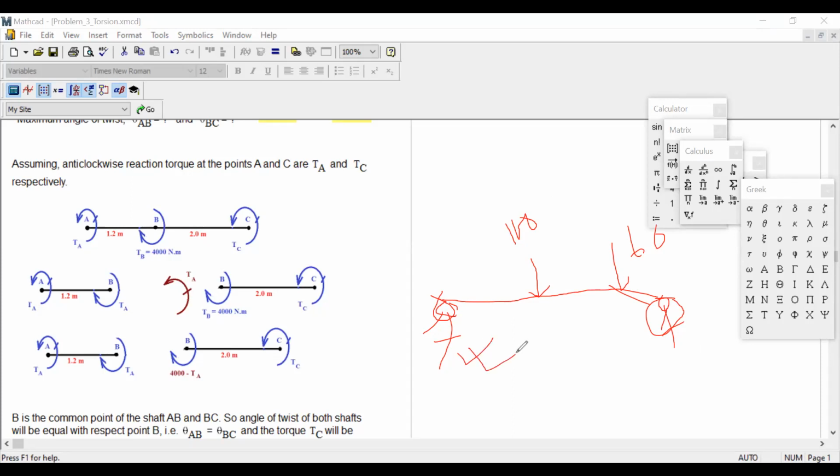But in torque, even if you take moment, this is not force into distance. We apply torque. So even if you take moment over here, TA should not be 0. Right? That means you have three values, TA, TB, and TC is unknown. So by taking moment or summation of force, you cannot figure out the value of TC and value of TA. So what need to do, like in axial tension member, you did a free body. So you have to draw a free body.